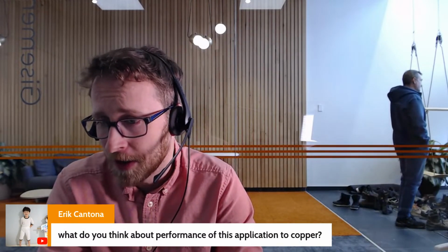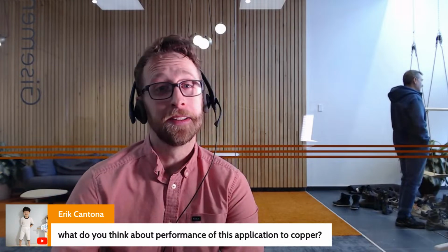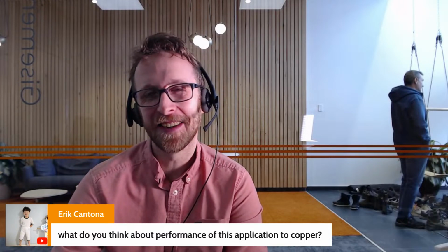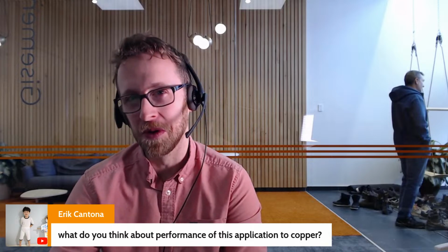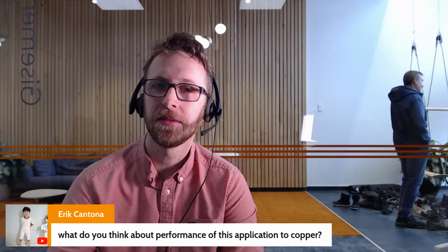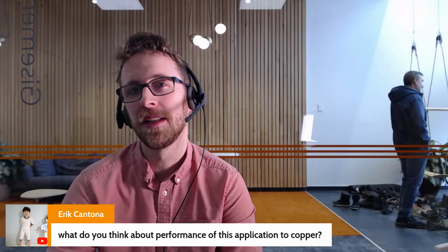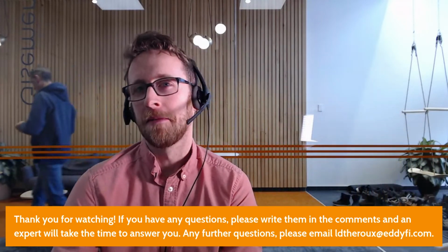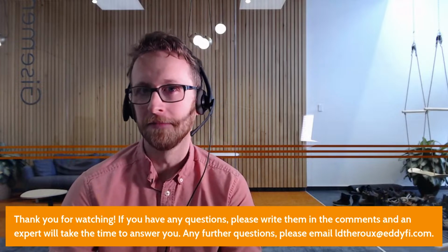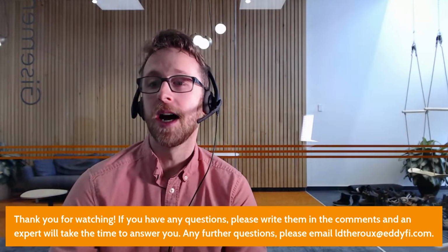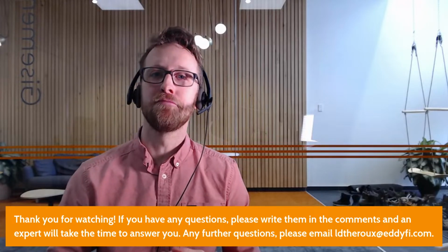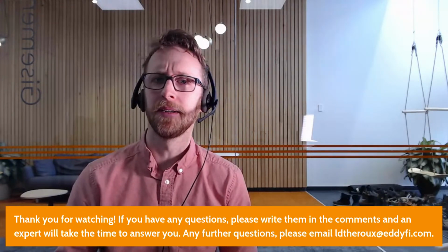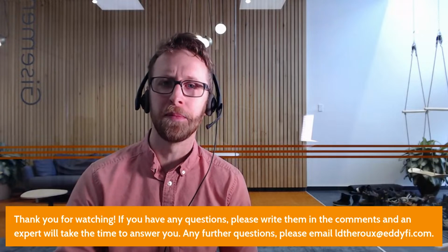What about the performance on copper? It's a good question. Copper would be much more conductive than most of the material that we tested and that we see for this kind of application. It wouldn't be impossible to do. However, because it is highly conductive, you will be limited in the depth of penetration and detection of that probe. This is something that you can tweak a little bit using lower frequency. However, you're going to be much better at finding a very, very small defect on copper just because it's so much more conductive. So what I would recommend is, depending on your need, we might have a customization option where we use maybe a lower frequency coil depending on your detection criteria. But it would be possible, yes.